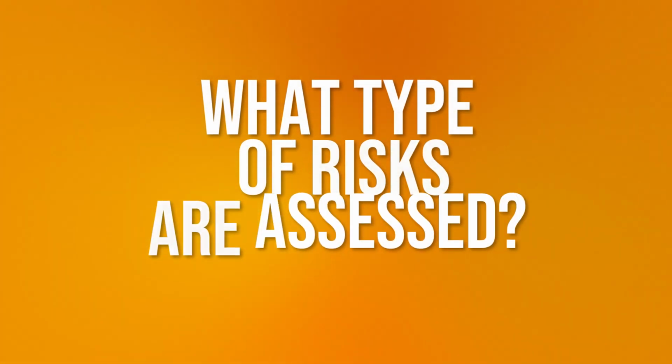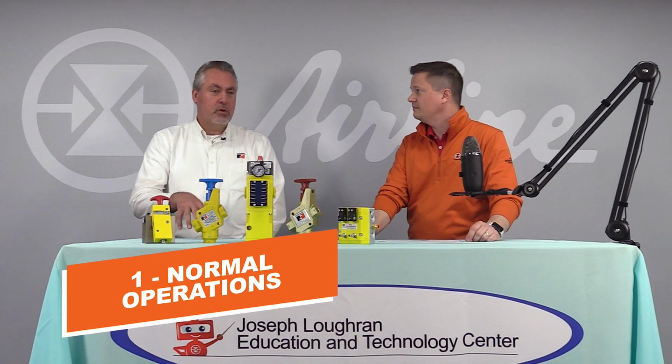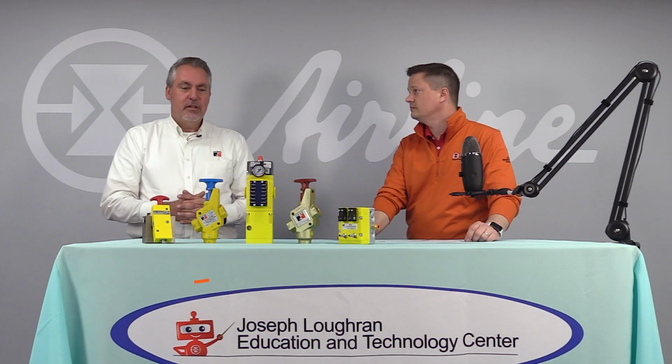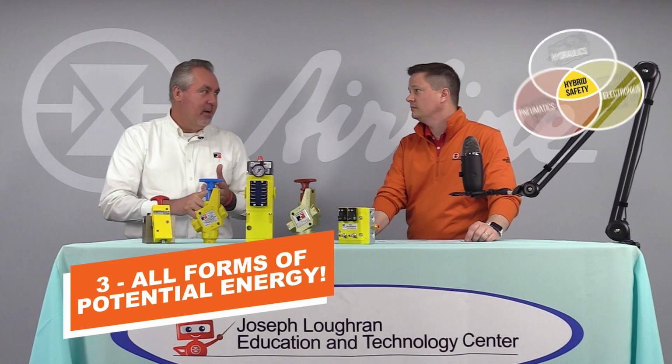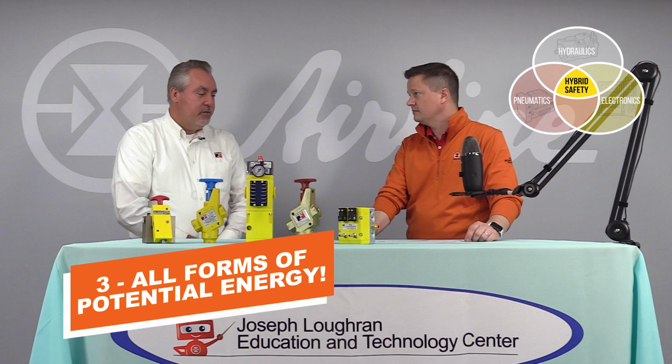So what type of risks are assessed? Well, most of the time, honestly, people will go out and look at normal operations when they do their risk assessment, and they'll ignore abnormal things like what happens when the machine jams, or what happens when I've got to do a changeover or cleaning. That's why we need to look at all modes of operation. And part of that is you should be looking at electrical, pneumatic, hydraulic, gravity. I mean, it's any source of potential energy you have to evaluate during your risk assessment.